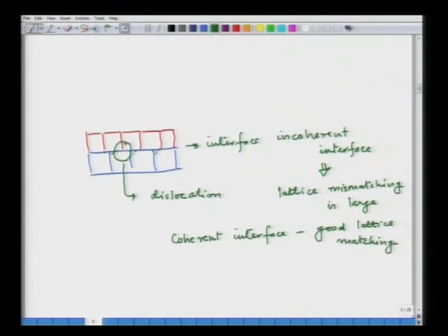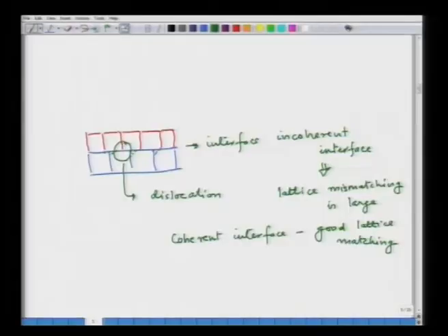So, this is another way of creating strained material. By that we create pseudomorphs which have different electronic structure, which have a different band gap and will emit different light, and that is one way of doing band gap engineering.